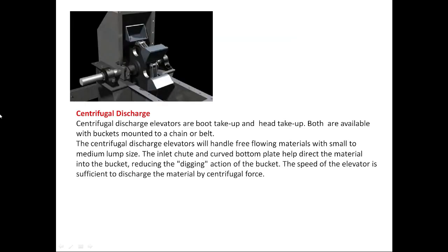Centrifugal discharge. Buckets for centrifugal discharge. Centrifugal discharge elevators are boot take-up and head take-up. Both are available with buckets mounted on a chain or a belt. The centrifugal discharge elevators will handle free-flowing materials of small to medium lump size. The inlet chute and cover bottom plate help direct the material into the bucket, reducing the digging action of the bucket. The speed of the elevator is sufficient to discharge the material by centrifugal force.